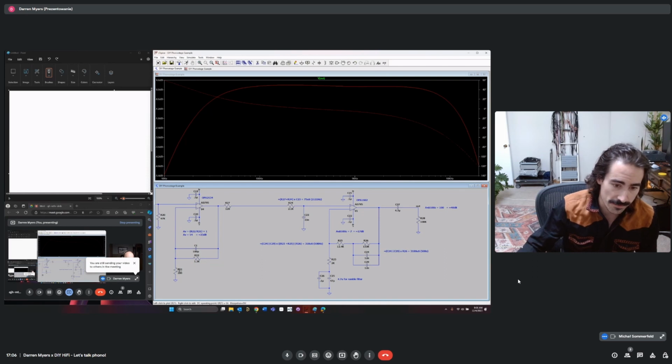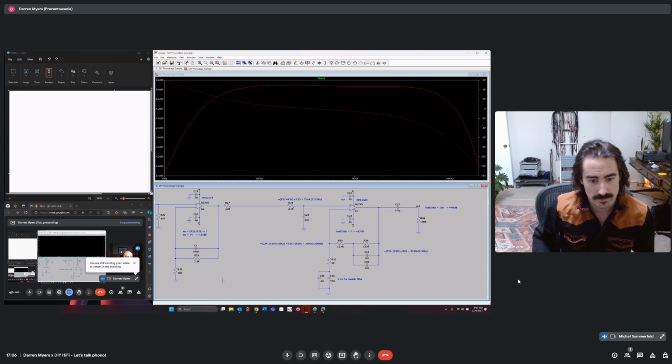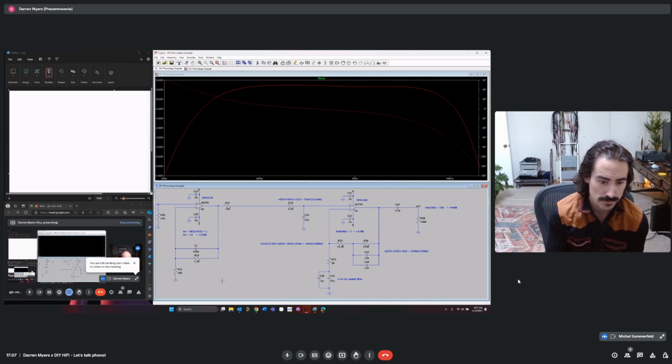And because of the configuration and the equation that we need to get our gain, R21 will always be a lot lower. So R21 tends to dominate over R22. I see. So it's kind of like the noise that is coming from the R22 is getting shunted by the R21. Yes, correct.